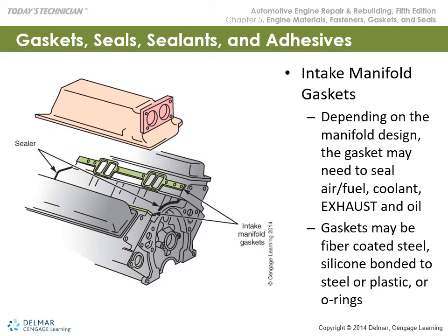So when we have intake manifold gaskets, depending upon the manifold design, gasket may need to seal air, fuel, coolant, exhaust, and oil. So there's a lot going on in some intake manifold gaskets. And they may be a variety of materials. So you got steel, silicone bonded to steel, plastic, and or O-rings. So you have to pay attention to what's coming off the engine and make sure your replacement parts and your gasket kit, everything is exactly the same that came off that engine.